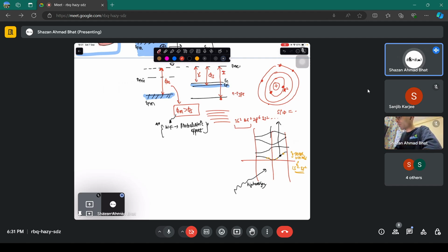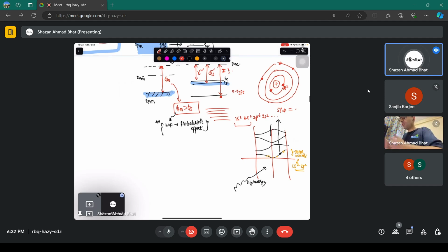But this is not mostly used in our case because it's a very destructive process if you play with the inner electrons. Mostly high energy physics people work with these electrons, but we are not concerned with them. So that's why people don't show these ionization potentials. We're mostly concerned with the work function. We're mostly concerned with the electron affinity. And now you have to interplay. Now you know this particular thing is the band gap of this semiconductor. So this is EC minus EF. You know all these relations from the earlier classes. Now you just have to play with these.